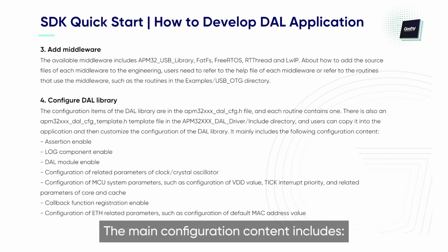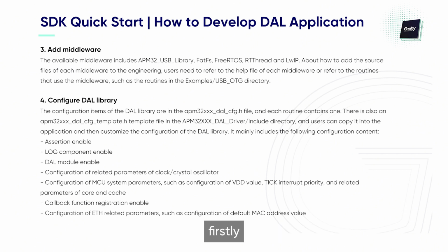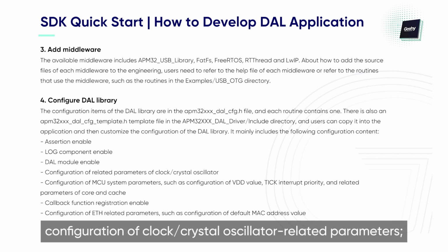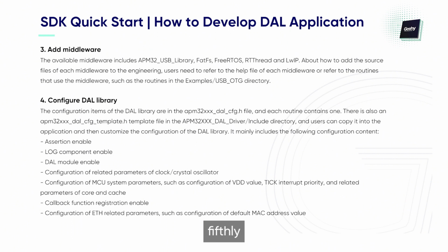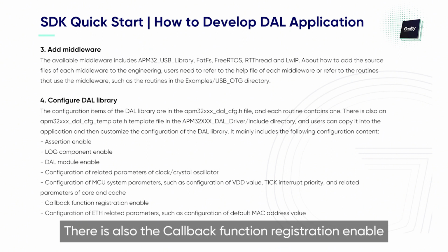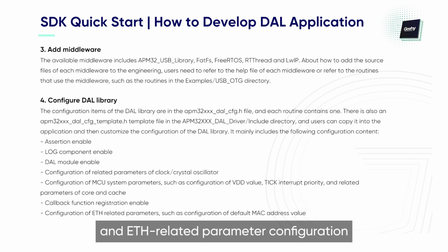The main configuration content includes: firstly, enable of assertion. Secondly, enable of log components. Thirdly, enable of DAL module. Fourthly, configuration of clock, crystal, oscillator-related parameters. Fifthly, MCU system parameter configuration. There is also the callback function registration enable and ETH-related parameter configuration.